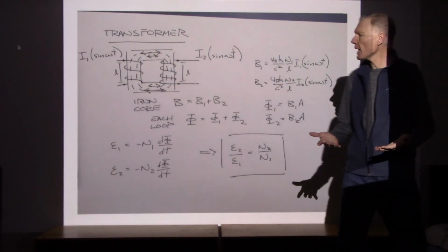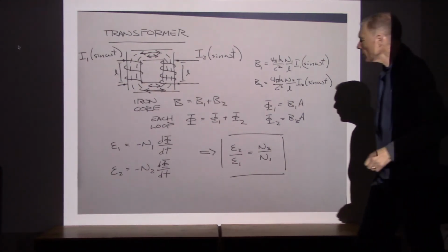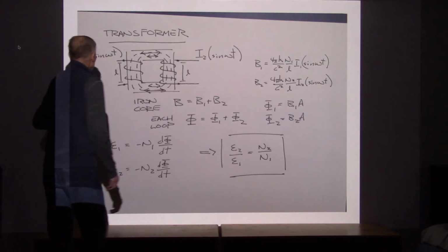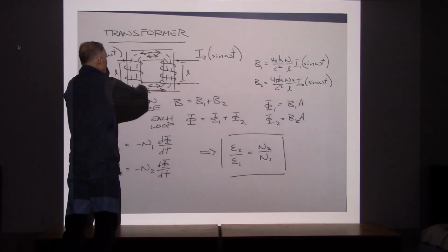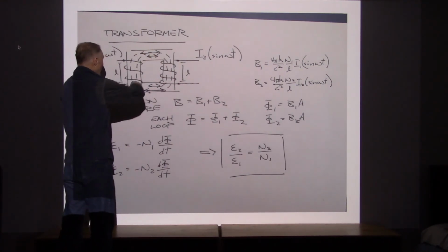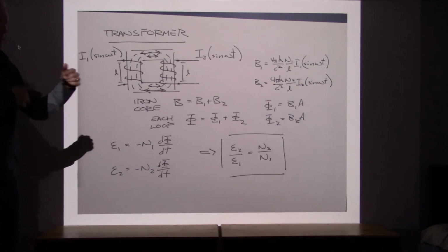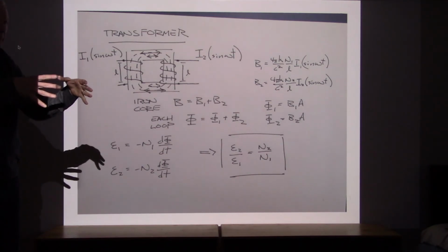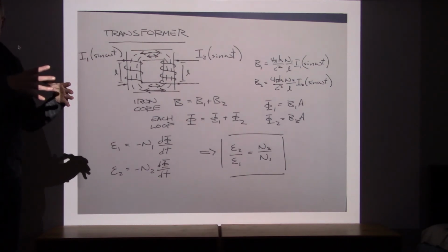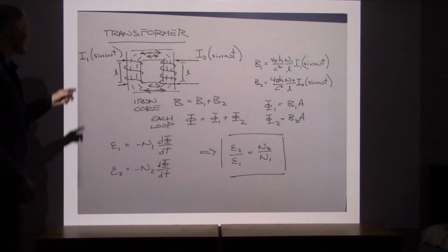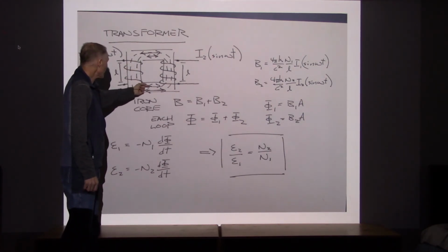Now, we do have to have alternating current to get a transformer to work. What happens is, if I send in direct current here, it will set up a magnetic field inside the iron. Now, the reason that we have the iron core is that anytime we use current to set up a magnetic field in a particular region, very likely the magnetic field is pretty localized. By using an iron block, we can redirect the magnetic field.